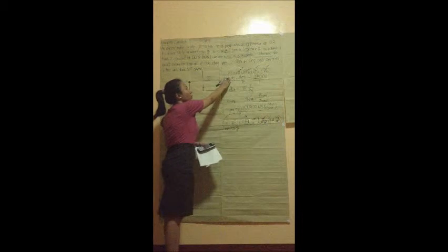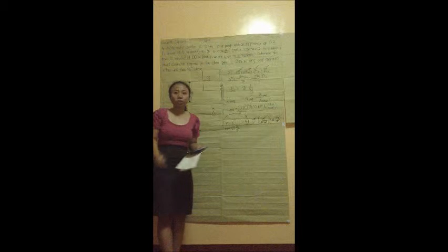Now we are going to get the value for the summation of the friction losses. The friction losses in this problem will be the summation of the line friction. And we can see that from this point, from the tank to the pipe, there is contraction. So we assume that there is friction due to contraction, which we will say as Fc. And we also put a reference point 3 so that we can name the properties of water here.